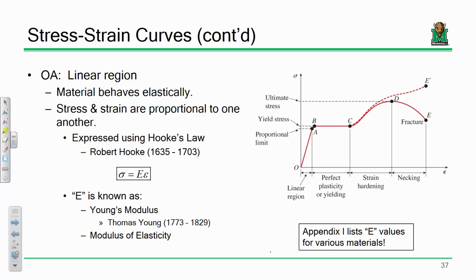So one of the things that we do in automobile design, particularly when we're looking at the frame or the body of the car that frames the car together, we purposefully design what we call fuses in engineering. Specifically, there are regions of the car that are meant to plastify, that are meant to deform, that are meant to absorb all that energy, so that energy doesn't get absorbed by you. You have a car crash and the car looks mangled, but if you're fine, then you did a good job. So that's sort of the point.